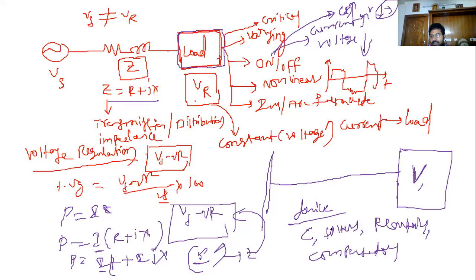Whenever you use capacitors, they not only regulate the voltage, they are also used for power factor correction. But the use of these capacitors on the load side again leads to some problems: switching events. When the capacitor is connected to or disconnected from the system, it leads to transients in the system, which we call oscillatory transients. Why do you use these capacitors? To improve the power factor or the voltage regulation. But using these capacitors also gives us some problems.